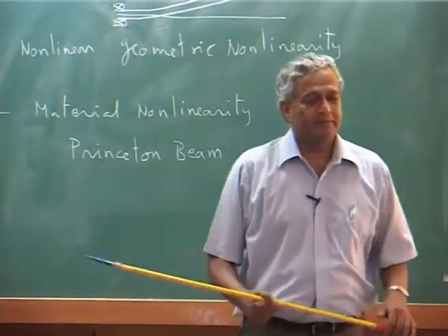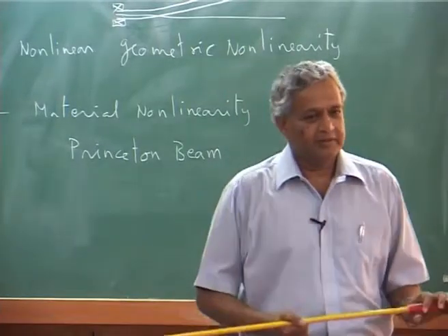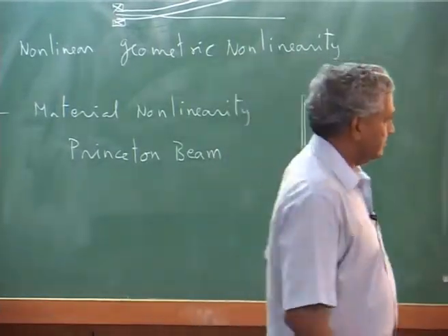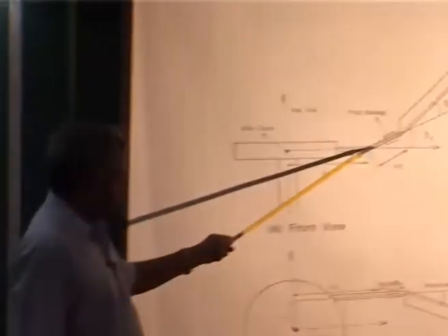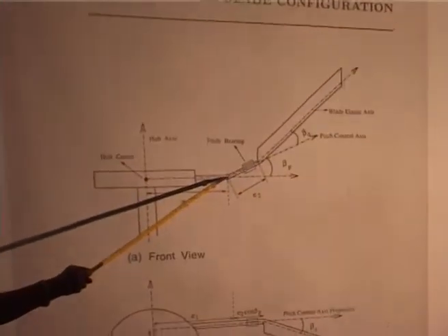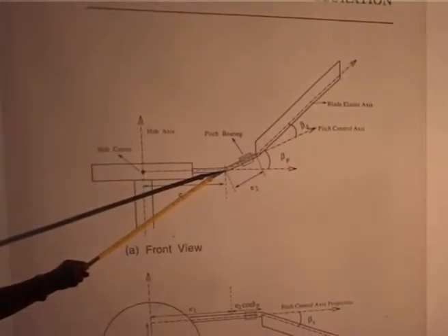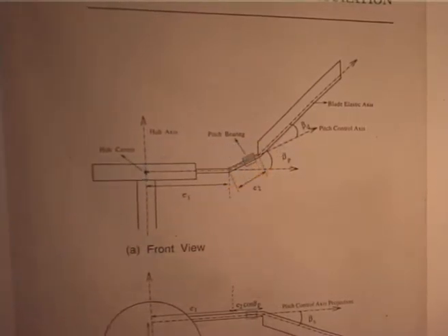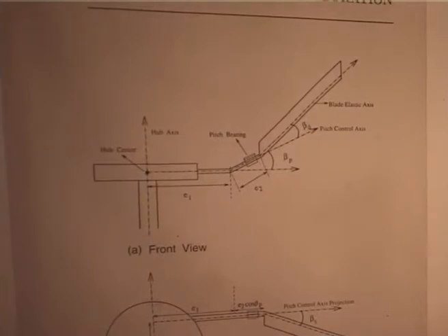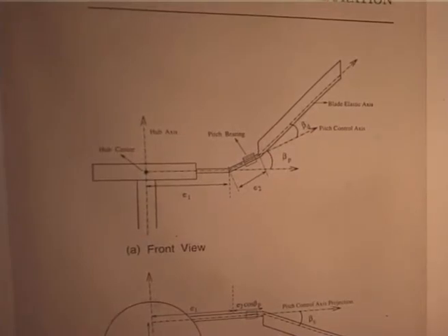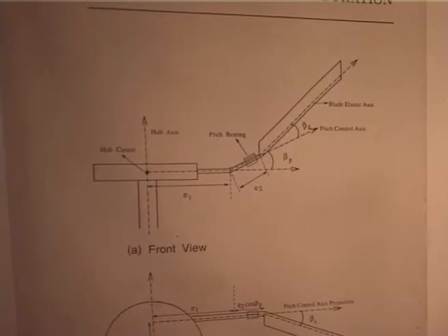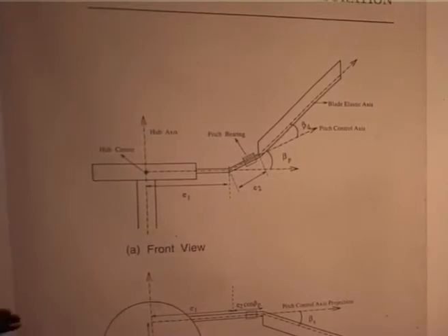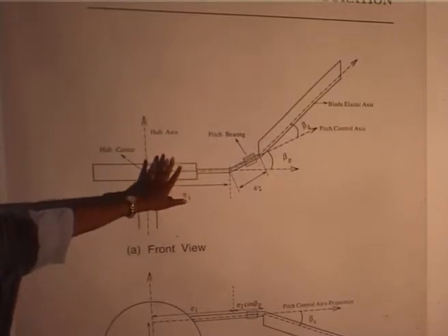But my doubt was, where the pitch bearing is, where we are giving a pre-cone angle, that point, that's a hinge, right? Here. Yeah. No, there is no hinge. Flap in this? There is no hinge in these things. Okay. This is the hingeless blade configuration I have shown. Oh, if you have a specific flap hinge, that we will come to that. That is where I said, this is just a configuration, I have not shown actual geometry.